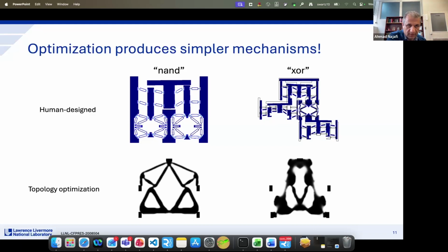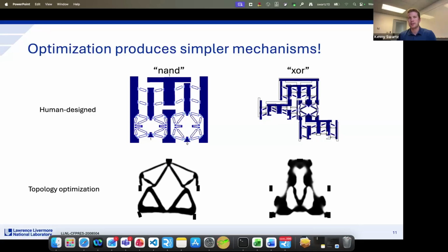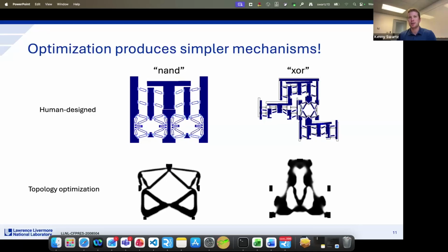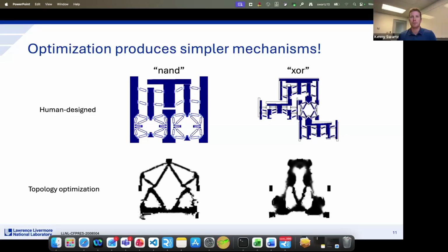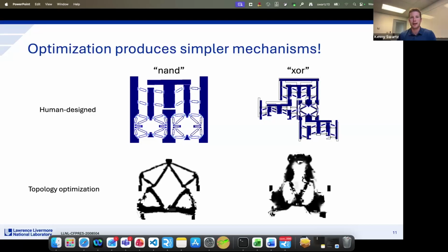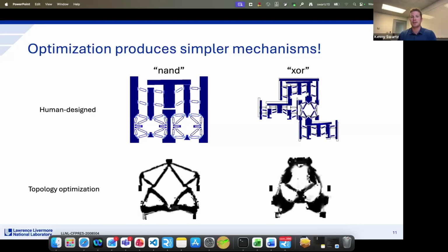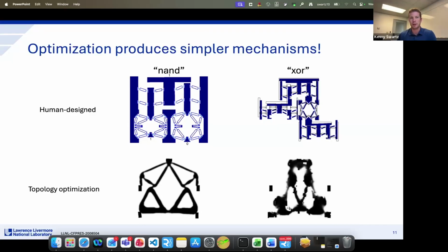Yes, into topology optimization. Right, and my mentality there is that it's not the buckling that we care about. It's the fact that when it buckles, it doesn't hit the performance goals. And so rather than put in a constraint to avoid buckling, what we really mean is we just want it to work. So we just had to make the model more relevant in the optimization so that the optimizer could drive us to a design that satisfied the logic, which implicitly meant it didn't buckle in that third direction.